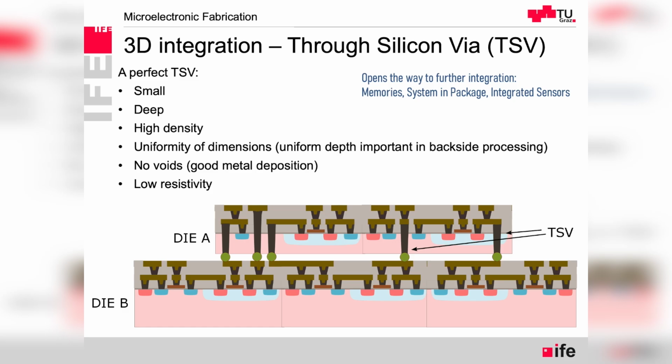If we would like to connect pixel to pixel with readout pixel to pixel, the best arrangement is to stack them on top, because then we can have a module, and next to it another module, and like that we can also make large panels. That's an example where it can only go through silicon vias. But also memories use multiple stacking, and many other applications.